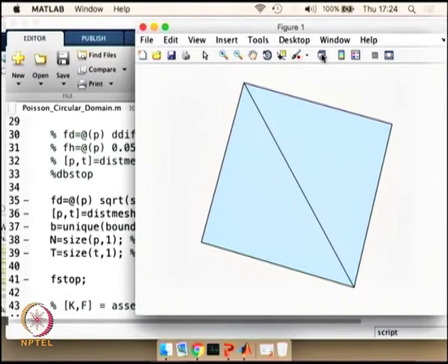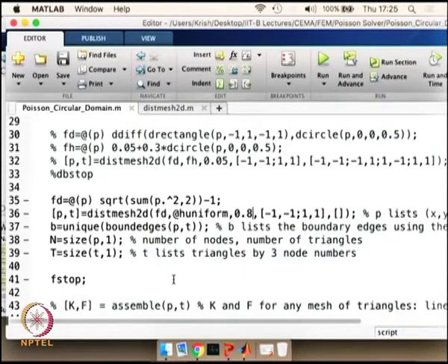The reason is that the starting point is minimum value -1 and the maximum value is 1. So inside a particular domain I can have maximum only 2 cells, because 0.8 plus 0.8 gives me 1.6, and the domain limit is 2. So putting 0.8 is going to be a very coarse discretization.